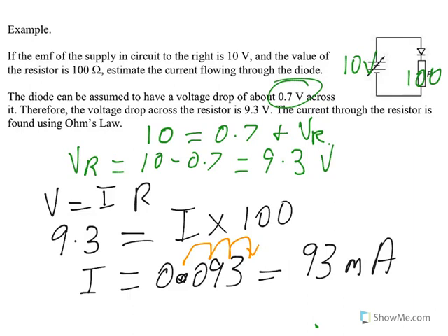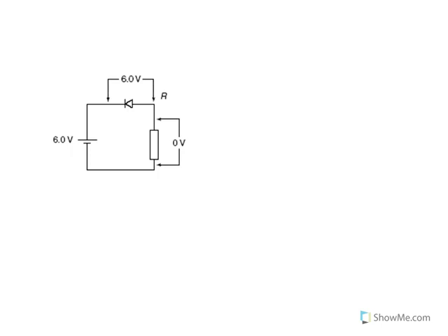Now, there's a little note in there. That was forward bias, so that's alright, conventional current flowing around this way, and that's all good. But just remember, you need to check, because if it's reverse bias, such as is the case here, we're trying to send the current around that way, and when we look at the diode, we'll notice that it's in reverse bias, it's got its wall up, won't let it get through.